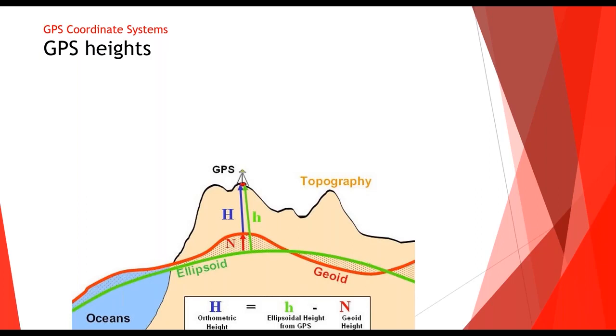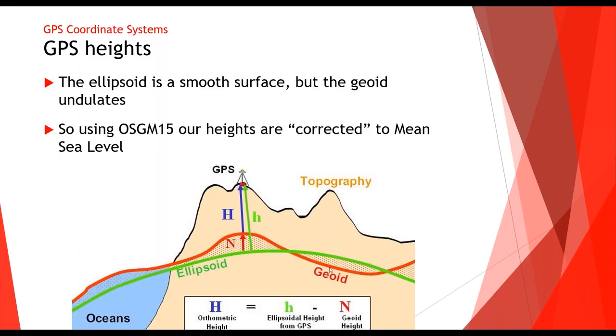But we also then need to know elevations. So as we all know, we reference height relative to mean sea level. What controls the height of the sea, the mean sea level? What we do know it to be is gravitational pull. Okay, so what influences that? Lunar cycles have a big influence over this. So what we need to do then is capture gravitational data right throughout the country, so then we can plot essentially where mean sea level would be at that given location.